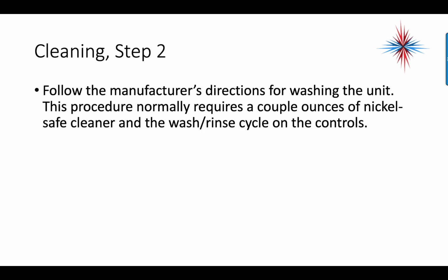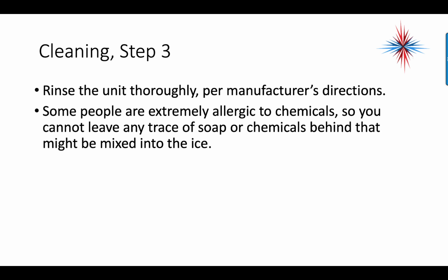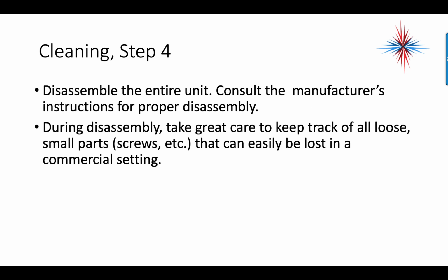Step 2, follow the manufacturer's directions for washing the unit. This procedure normally requires a couple ounces of nickel-safe cleaner and the wash-rinse cycles on the controls. Most ice machines come with a control setting that is a wash setting, and it will actually cycle this through almost automatically on the water side. Then you're going to rinse the unit thoroughly. Again, follow manufacturer's directions. Some people are extremely allergic to chemicals, so you cannot leave any trace of soap or chemicals behind that could be mixed with the ice.